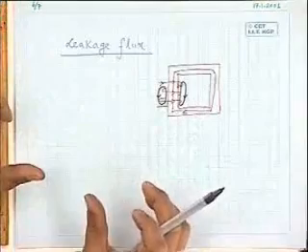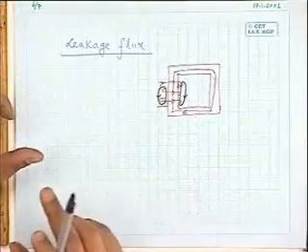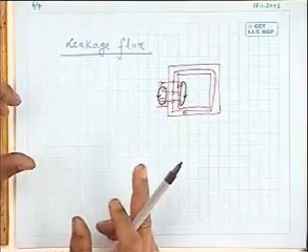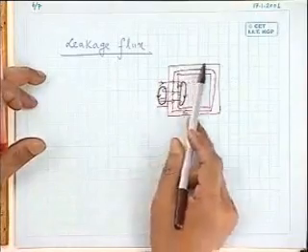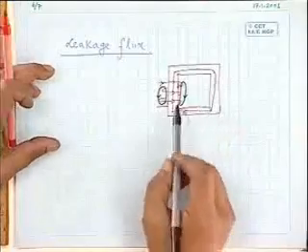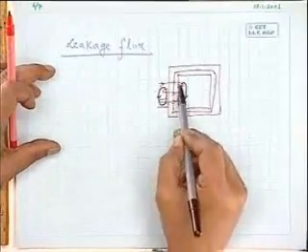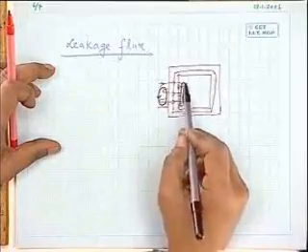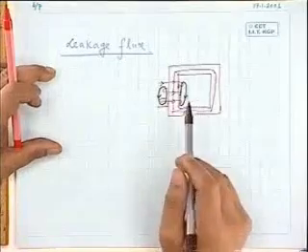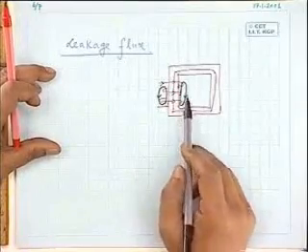Through the air gap, it will never, of course, because given an MMF, there are two parallel circuits. One is the reluctance of the air gap and another is the reluctance of the iron. Most of the flux lines will be confined to the iron because its reluctance is much less compared to the air gap. But nonetheless, if you consider a closed path here, you find some current is enclosed, some flux will be driven here, depending upon this total MMF divided by the reluctance of the air gap, etc. Therefore, there will be some leakage flux also present.